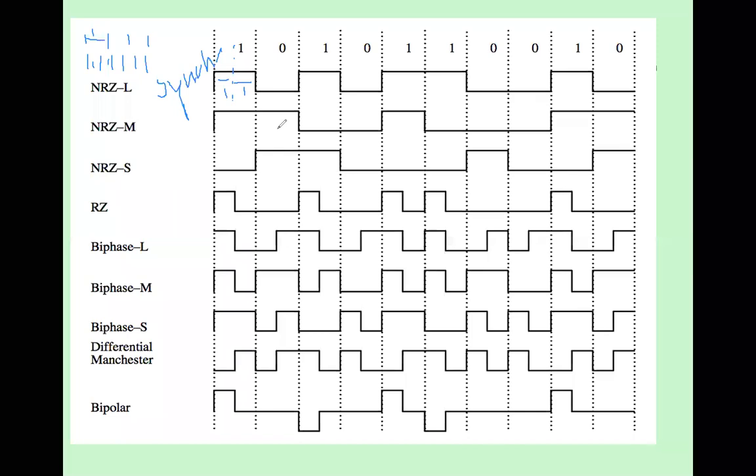So how can this information be transmitted? We can provide this information whenever the signal is changing. Here the signal changes and here the signal changes. So whenever the signal changes, the computer can identify the clock tick duration. So it is very important that your signal should change, because as soon as the signal changes, the computer gets this timing information and can synchronize. This is one concept that you should understand.